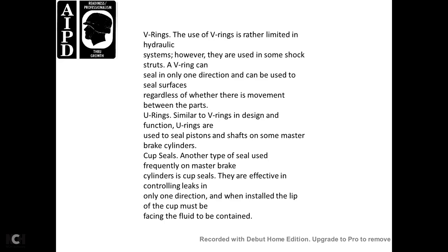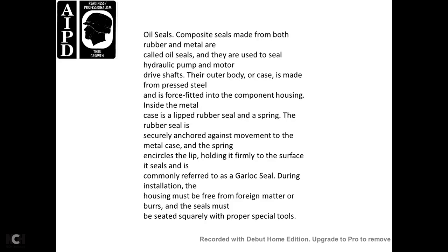Cup seals. Cup seals are another type of seal used frequently in master brake cylinders. They are effective in controlling leakage in only one direction. When installed, the lip of the cup must be facing the fluid to be contained.